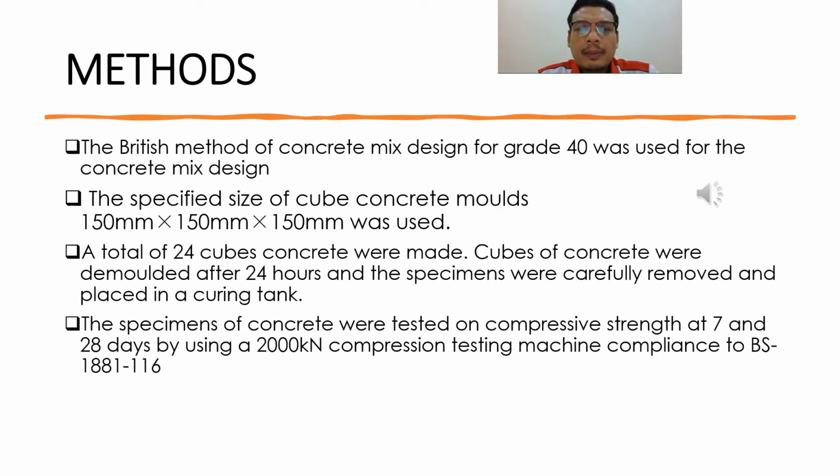This is the method conducted in this research. The chemical composition of fly ash was determined using X-ray fluorescence, XRF. Sodium silicate was dissolved using distilled water and left for a day as preparation of the solution before mixing in the concrete. The casting of concrete was done in cube mold measuring 100 mm times 100 mm times 100 mm. A total of 75 cubes